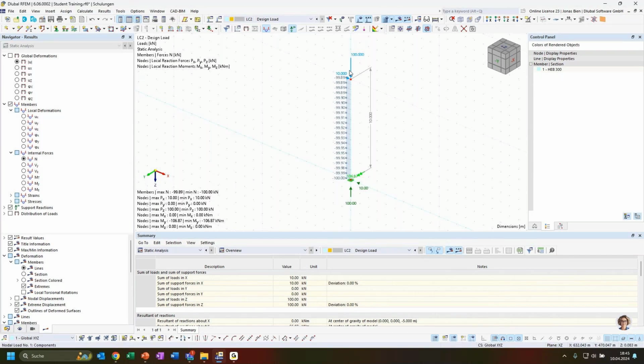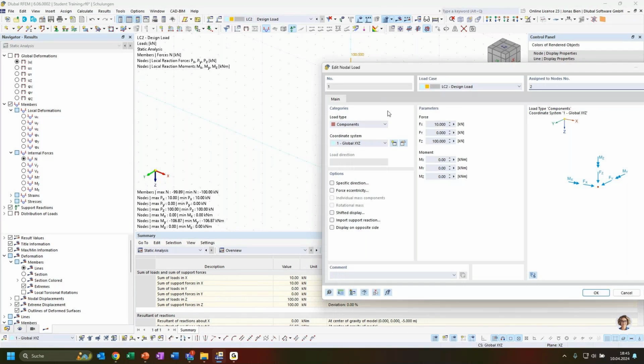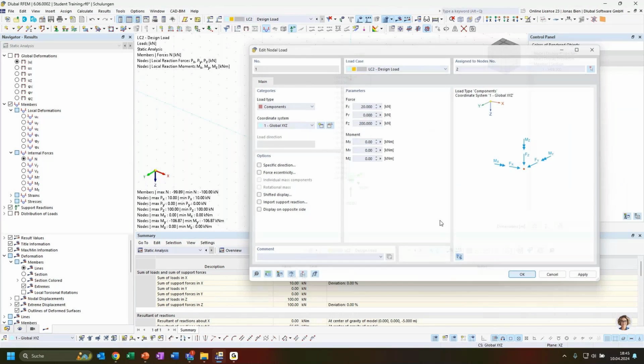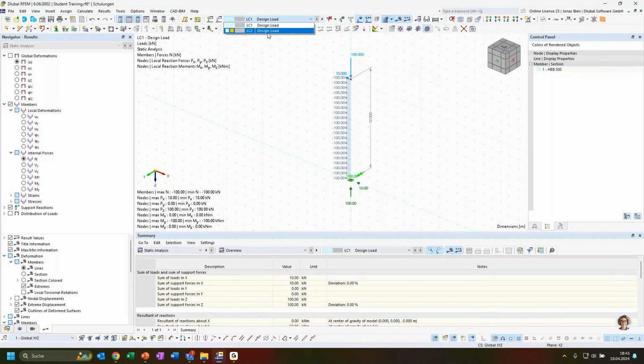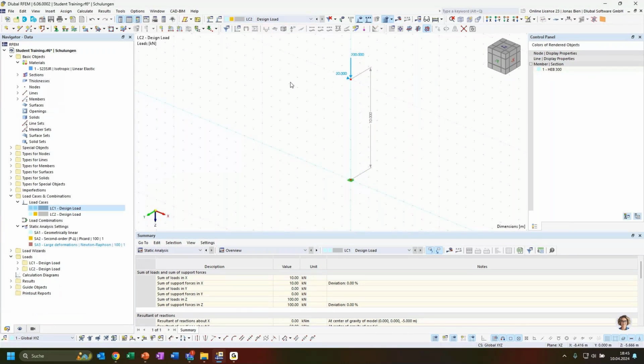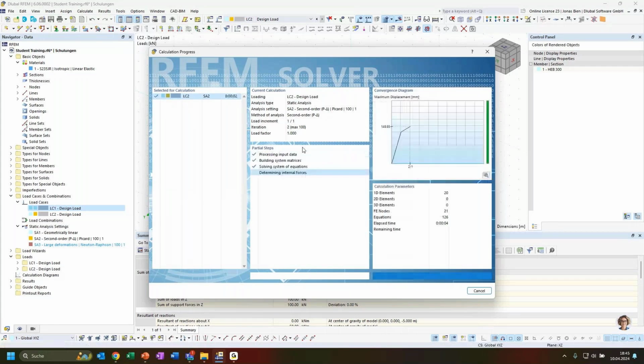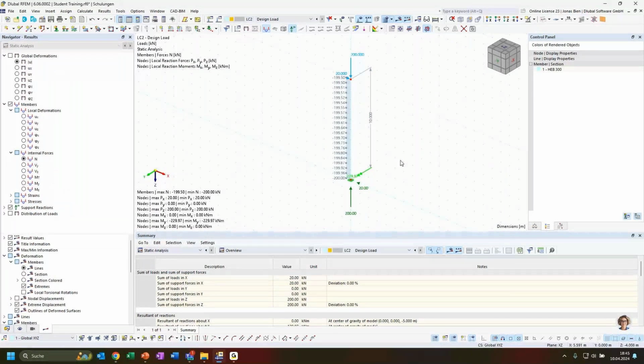So, for example, in the second load case, we can double the load. And I want to show you, let's compare the reaction we are getting now. As I said before, we had an increase of the resulting bending moment at the column base of 7%.